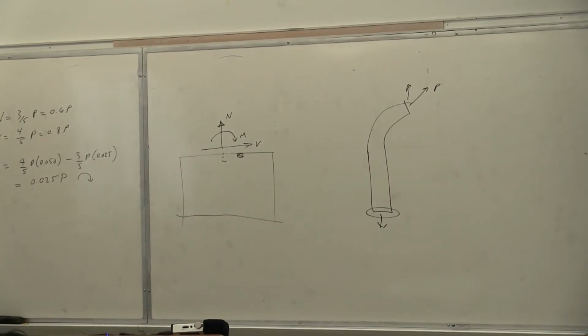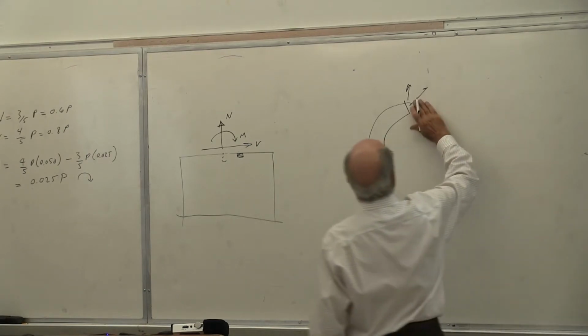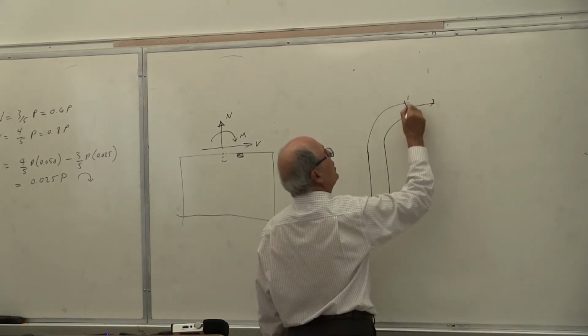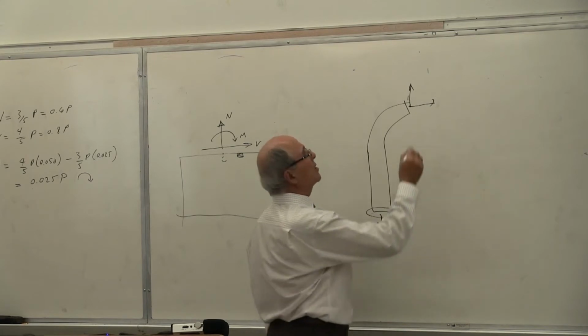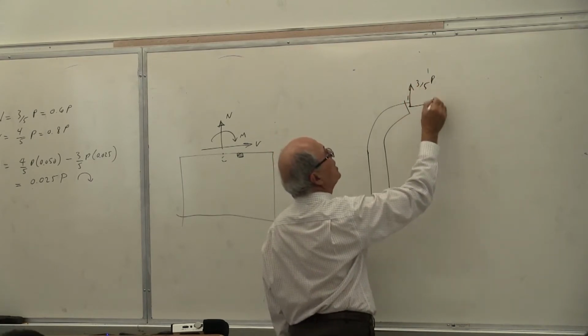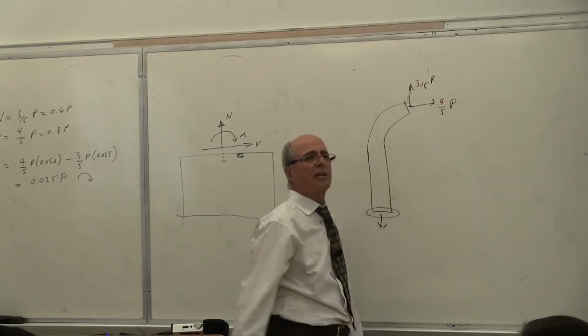See, when I see something that I do not understand, I want to find where that is coming from. Why can you not see that so simply? There is one vertical force, one horizontal. Look, this is all I'm saying. Divide this into two components. Yes or no? Yes, that component is 3/5 of P. This is 4/5 of P. Is that correct or not?